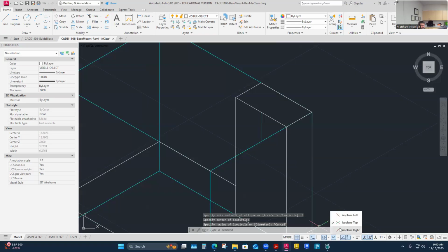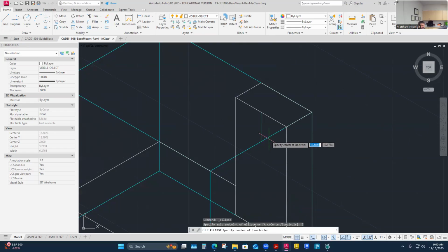And that's probably the only major trick to these drawings, really, is getting your ISO circles on the right plane. ISO circle. Because it's just driven by diameter here as well, or this one's driven by radius, right? So I think it's to specify the radius of this ISO circle. So mine is a half-inch diameter circle on our drawing. It's a quarter-inch radius. So that is that.